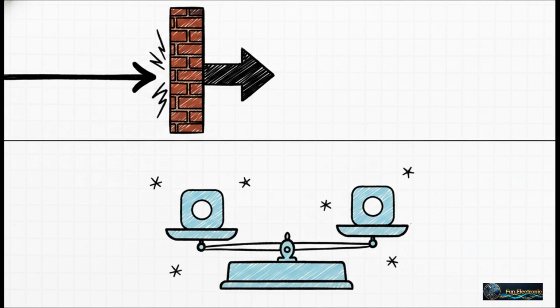in a closed loop. Rule number 1, infinite input resistance. This basically means absolutely no current flows into the input terminals. And rule number 2, the op-amp constantly drives its output to keep the voltages at both of its inputs exactly equal. Keeping these two rules in mind makes analyzing this whole circuit surprisingly simple.